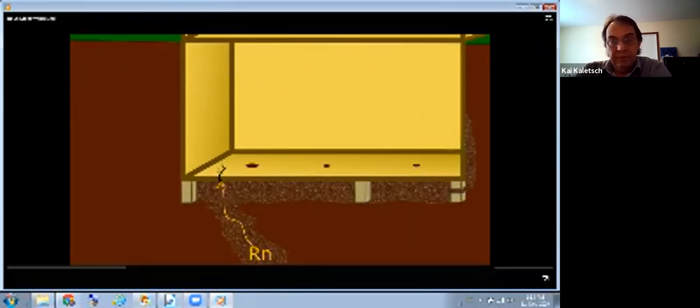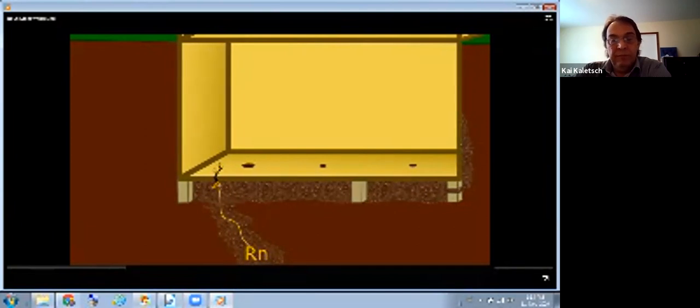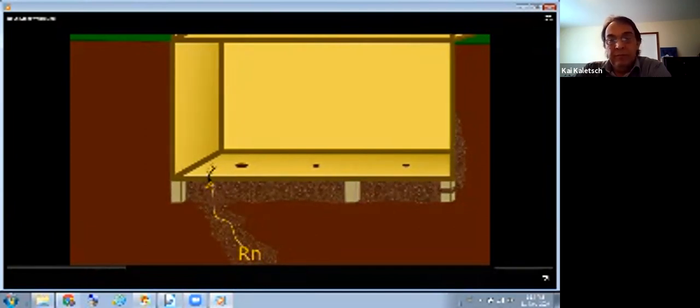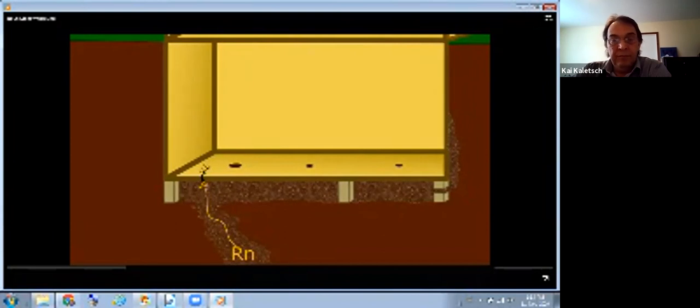The usual mitigation process would begin with a communication test, where holes are drilled through the slab. The mitigator would make a larger hole and apply a shop vac to see if there is a connection to the other holes. Normally that test would be made wherever the most convenient place for a mitigation system would be. In this case, that might be the hole on the far left.